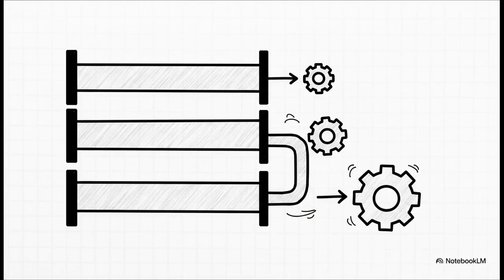Let's zoom in on the PAL architecture for a second, because it actually presents a really fascinating engineering trade-off. PALs are generally way easier to program than PLAs. But since the OR array is fixed, you hit a unique structural constraint. Product terms absolutely cannot be shared among 2 or more OR gates. Every single output gets its own dedicated set of AND gates.